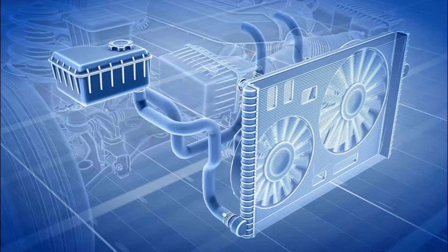If the level of coolant falls below the minimum limit, the engine cooling system suffers. In the engine cooling system, the radiator fan starts its operation when temperature exceeds a particular temperature value. It helps in lowering the coolant temperature by blowing air through the radiator fins, thus removing heat from the coolant at a faster rate. It is regulated by the data from the coolant temperature sensor.